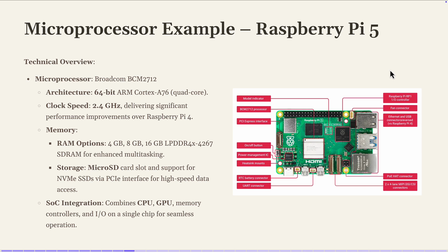So yeah, and this is powerful. But sometimes, for example, if you want to plug a power-greedy device like a laser or a 3D LiDAR, maybe it cannot work on these type of devices. So one time I had a robot with a Raspberry Pi, and I wanted to attach a depth camera. So depth camera, it gives you both the RGB camera and also the depth, which is the distance of the object in the picture. So it's a 3D. So the power requirement of the depth camera, I think it was around maybe 19 volts or something much bigger, because I connected it through the USB.